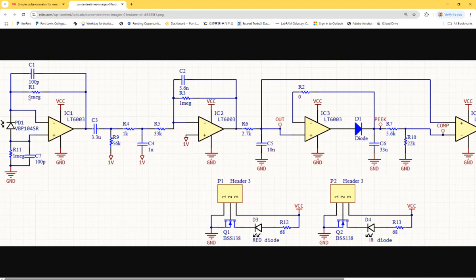And the capacitors are doing what? These are filters, right? If you put a capacitor in parallel with a resistor like this, it's a low-pass filter, and you can calculate the cutoff frequency of this pair. It's 1/2 pi RC. So you can easily calculate the cutoff frequency of that low-pass filter. Same as this one, it's also a low-pass filter.